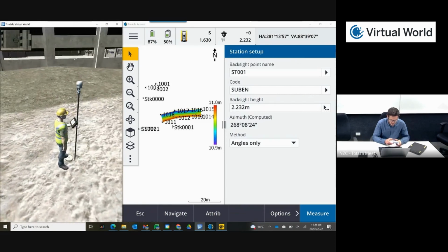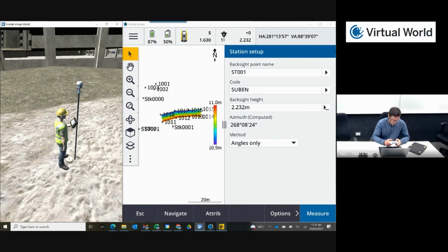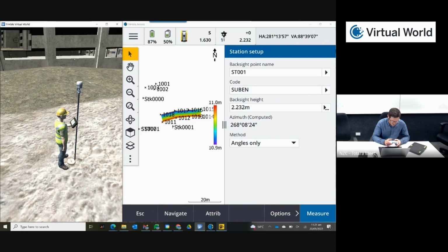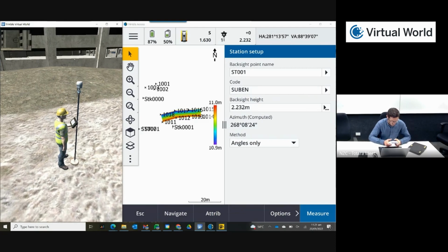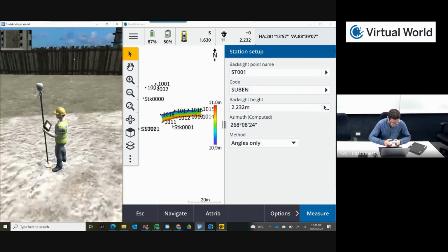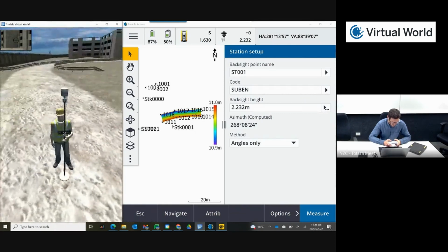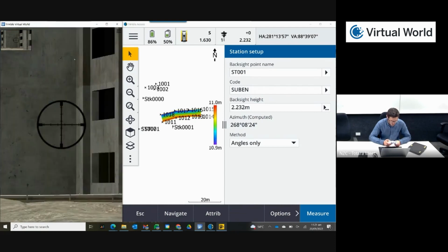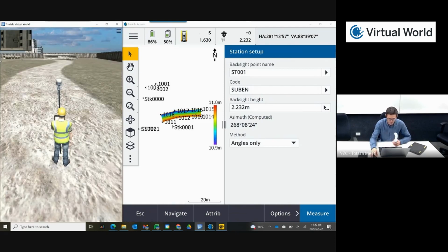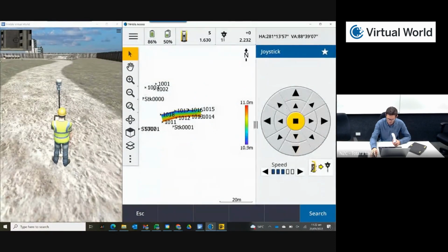Usually as a surveyor, we need to place our user perfectly on the scene, on the control mark. On this one, I'm going to use a small keypad for placing my surveyor. I can work around, and now I feel like I'm pretty much on the control mark. We could again take control of the total station and turn, but I can do it as well from Trimble Access, take control of the joystick, and finally do the turn.